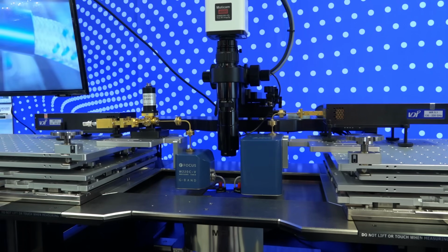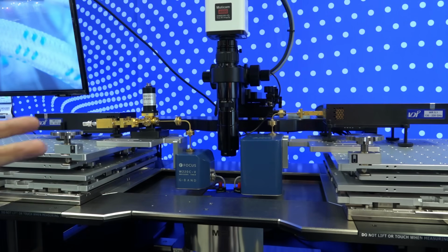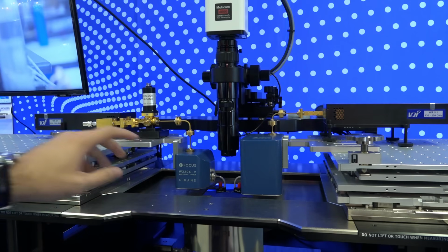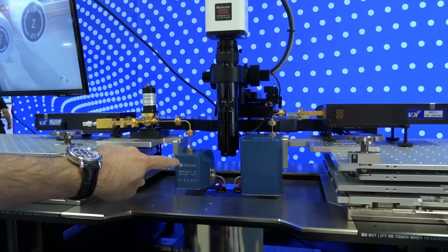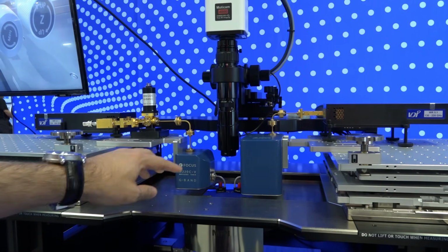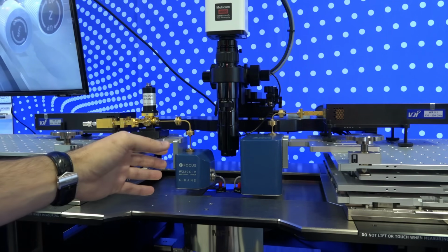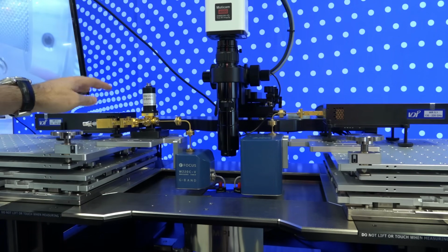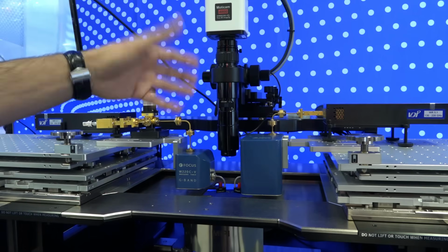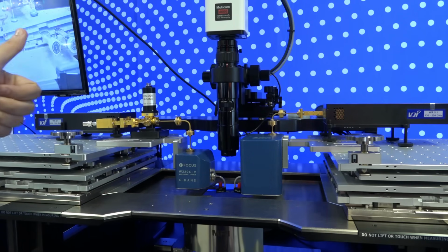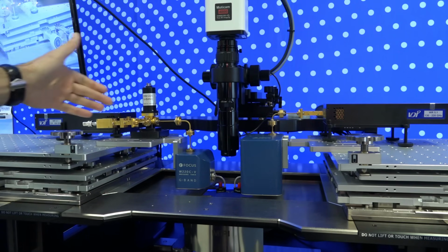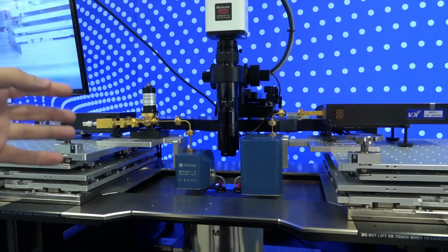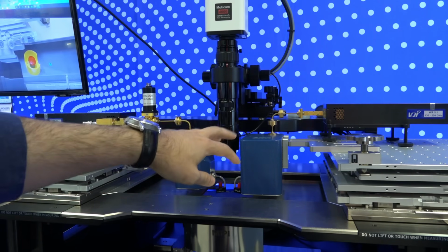So you need things like switches, noise sources, remote tests for S-parameter measurements, and of course tuners. So here at Focus Microwave, we have this G-band tuner in the front. You can see the G-band tuner directly connects to the probe, limiting any of that uncertainty, and then it is going into a switch that allows you to switch between an S-parameter head. So here you can do your S-parameter calibration, part number one of doing the noise characterization, and then you have a noise source over here which then goes through the tuner, allowing you to completely extract all of the noise parameters. On the other side, there is a down converter.